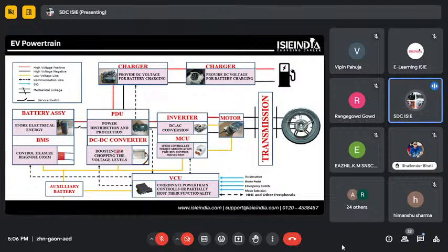So from here you can see that the DC converter is connected with the auxiliary batteries and the auxiliary connections. Now I'm coming to the PDU giving power supply to the motor controller unit, or the inverters, where we run some AC appliances, some AC compressors. For that we also need DC-AC conversion, depending upon the motor, like a permanent magnet synchronous motor, SRM motor, induction motor, or a BLDC motor for a three-wheeler setup.